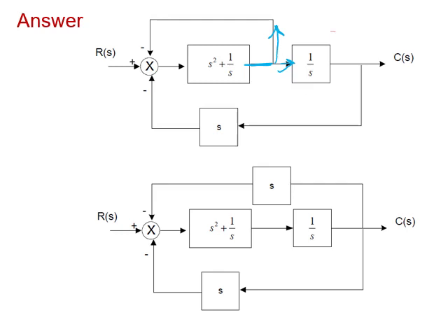So if I do so, I'm going to find that 1 over S will come here. You see, when I move this one to this location, it's going to be as you see here. And the other branch, this branch, will take the reciprocal of this value, meaning 1 over this value. 1 over 1 over S is equal to S. That's why we put S here. So now the shape of the block diagram is as you see here.